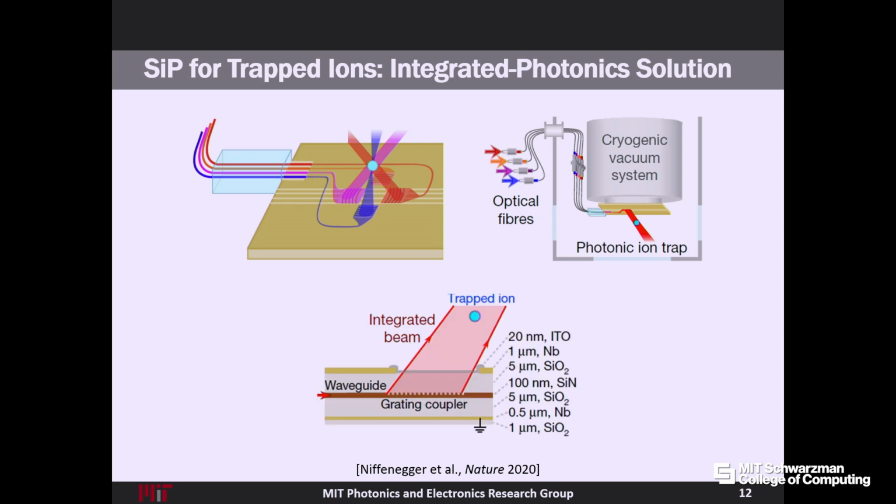And one of the very key components for this is these optical antennas on chip. So what that would look like is you'd have your silicon photonics waveguide, that dielectric waveguide that's confining light on your chip. And then you'd have some little, what we call grating coupler or grating antenna that is going to take that light off the chip and then scatter it up to your ion. What that physically looks like is you have your waveguide and you pattern these little perturbations in the waveguide. That causes scattering at each of the perturbations. If you design them just right, you can get all that light to emit up and to the ion through those metal electrodes that we patterned earlier.